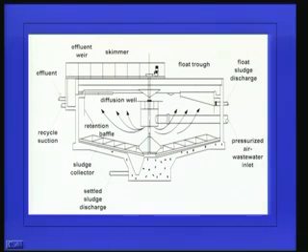So this shows the picture of a gravity settler. It is nothing but a sedimentation tank. The only thing is that when we design it, the overflow rate, loading rate, and cross-sectional area should be provided based upon the sludge thickening characteristics. This is a circular type sedimentation tank. This is the entrance of the sludge, and it gets distributed like this. Okay, this is the pressurized wastewater entrance. It comes here and gets distributed like this. Here it is getting settled, and clear liquid will go out like this, and sludge can be collected through this. This is the sludge collector, and here we have a retention baffle.